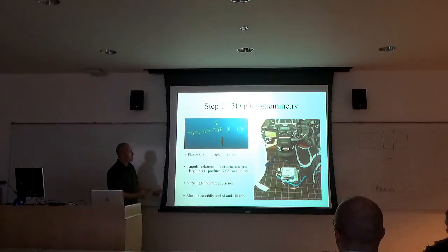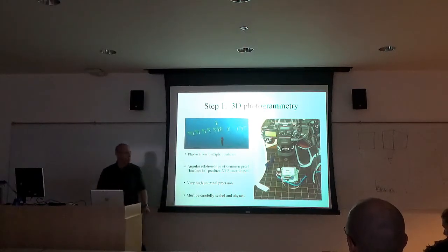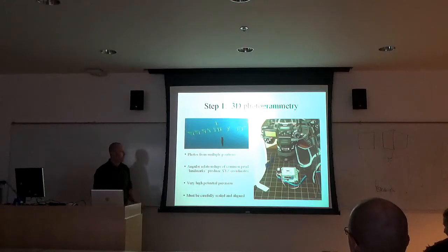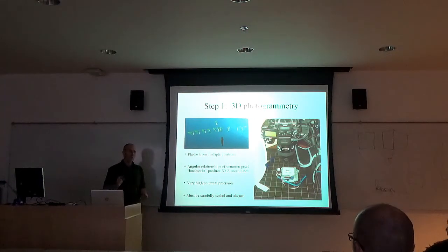So for the microblades, I've got this macro setup. I built a little microscope stage out of a couple DVD drives pulled out of old Xboxes, and a little servo motor. And so I stick the microblade on there, and the stage moves very, very gradually, and I take a bunch of photos. I usually like taking about 20, it works with as few as 8. And then I get about 2 million three-dimensional data points for the microblade surface.